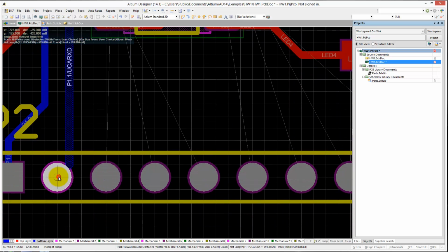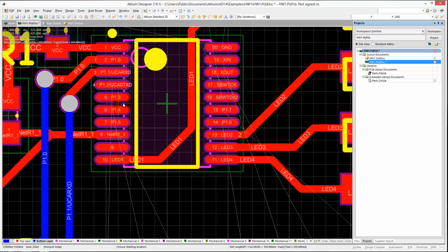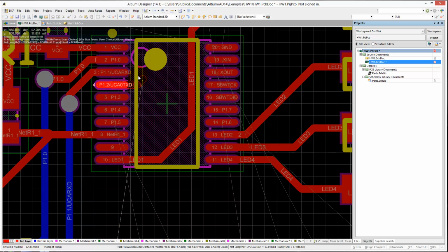And we go down here, connect it, switch back up. Using the star key while you're not in routing will also switch you back to the other layer. It basically toggles between the two layers. So here in this case, let's go up here, go to the lower layer.